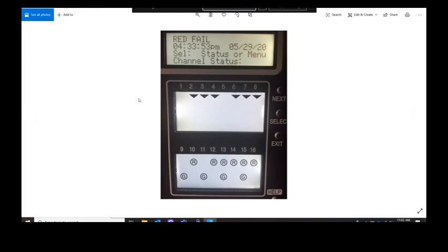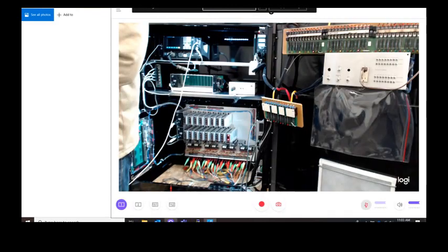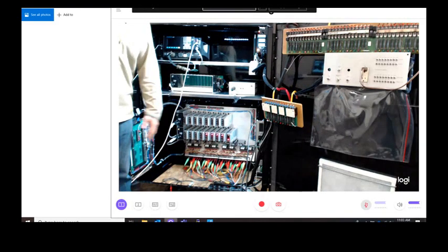And then if you notice, channels 1 through 8 all have arrows above them, but not 1 and 5 because it goes to the flashing yellow arrow. But I have indications under 9 and 16. The reason why is the upper BIU, I'm jumping around a lot, try to bear with me.